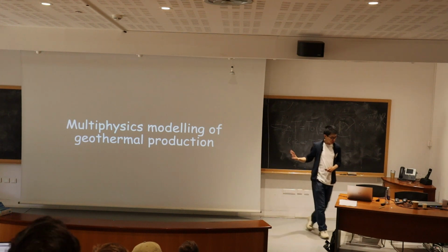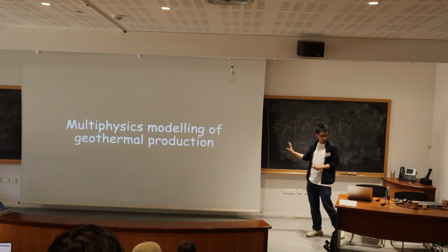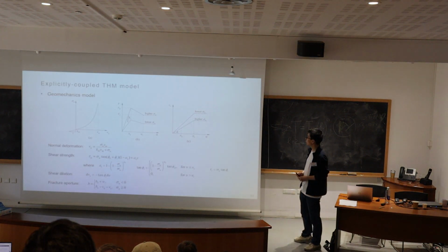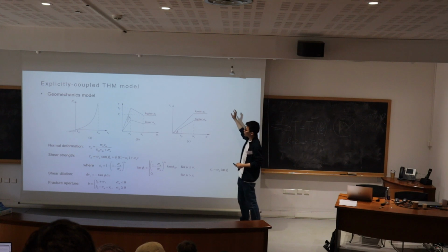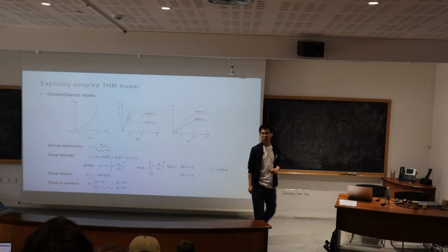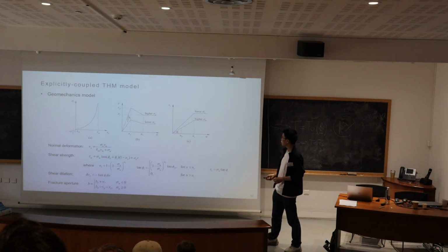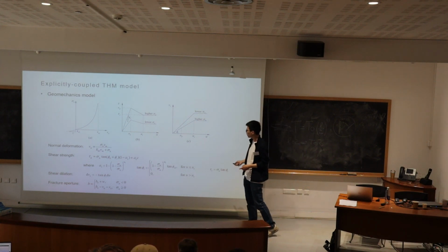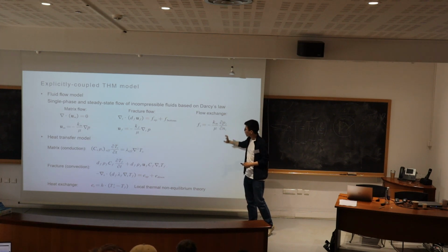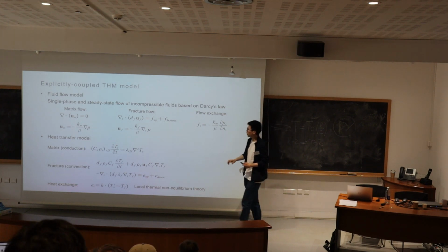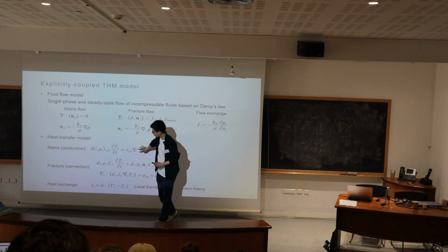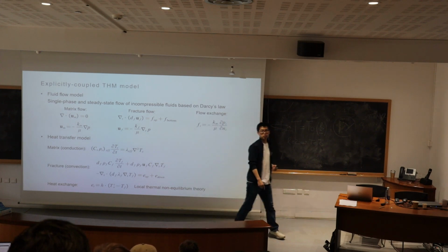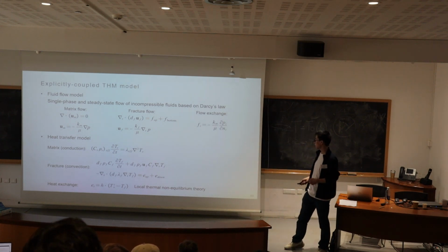Now we move to another application, which is related to geothermal production. Here I use an explicitly coupled model. Similarly, we model the geomechanical behavior considering the aperture and the shear deformation behavior, and we model the flow and heat transfer in the system. For the heat transfer, we consider the heat conduction inside the matrix, and we also consider the heat convection, which is more dominant in the fractures.